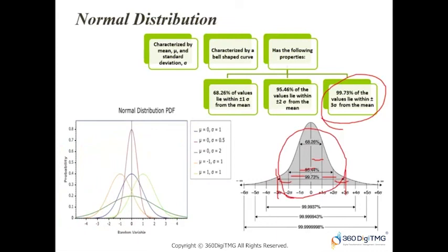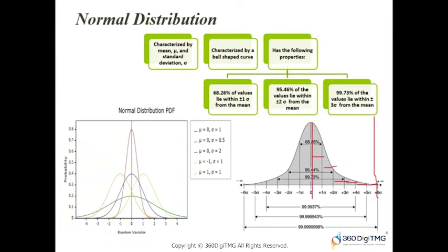No, my dear friends, you'll go wrong in this interpretation if you interpret in this way. 6 sigma means there has to be 6 standard deviations which fit in from the mean to one side of the specification limit. 99.999998% of the data points or of the products meet the specification limits. That is how you will have to interpret this. Or it can be on the other side also. If there are 6 standard deviations from mean to the other side of the specification limit, it is called a 6 sigma process.